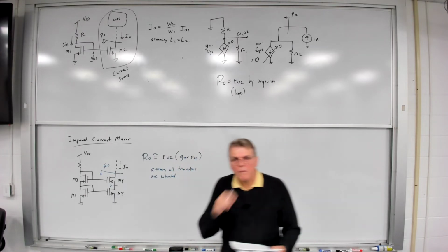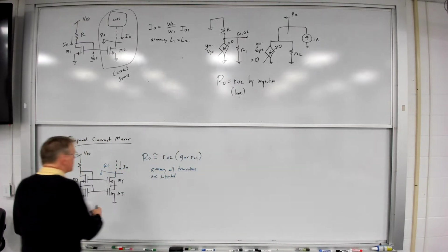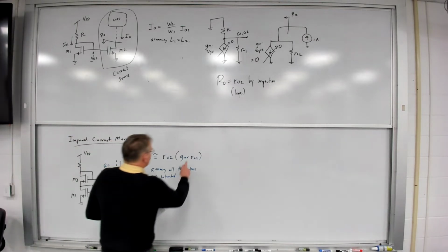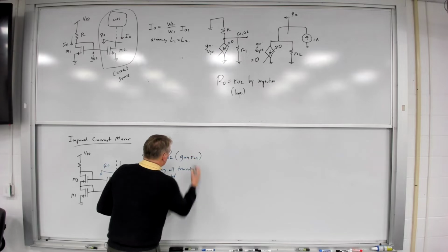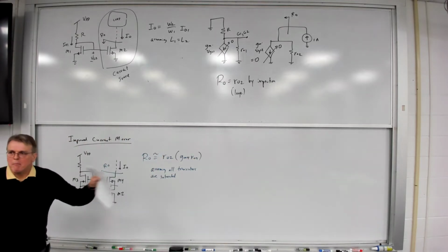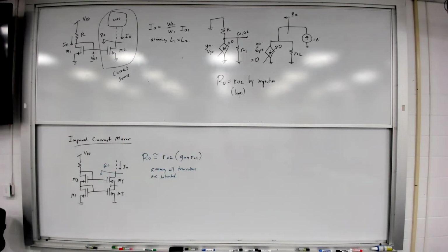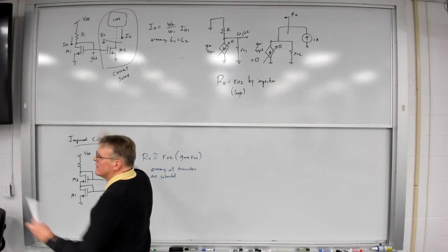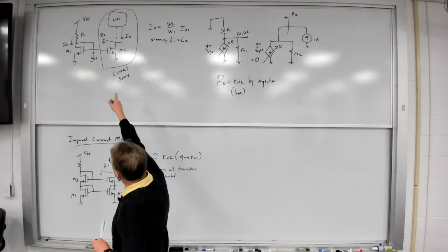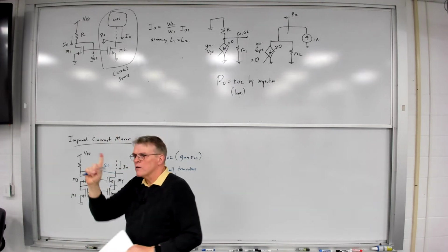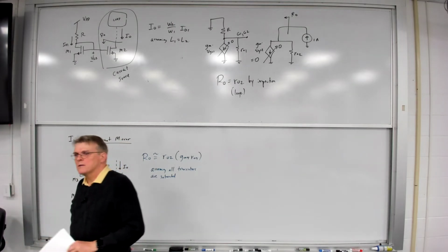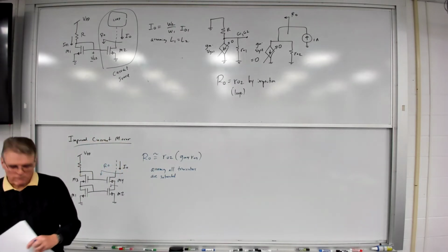So again, we can now see how we can take a lot of these clever little ideas and start combining them together. It should be GM4. There we go. So we can see how we can combine these concepts together into the same circuit. And you know, we can actually do some other interesting things. Once you create a current mirror, you're not confined to mirroring the current just once. Because keep in mind, VGS is just a voltage. We can take this idea even further.